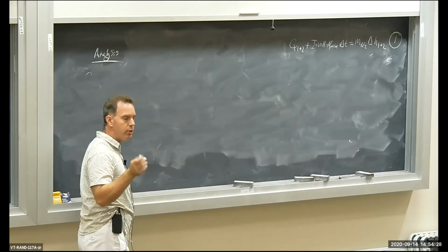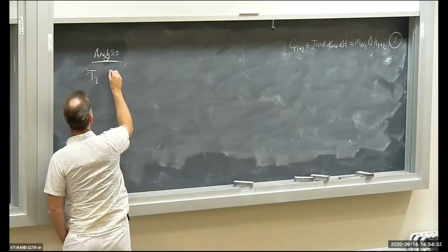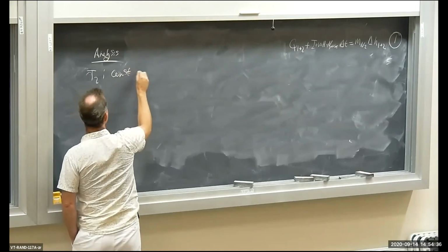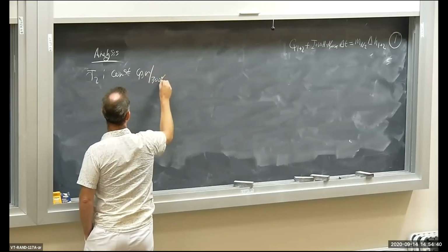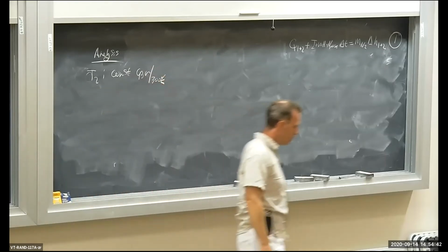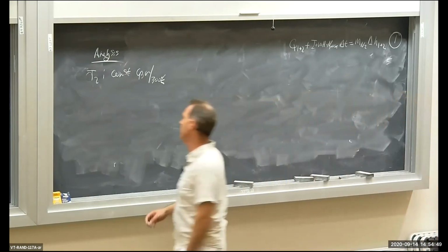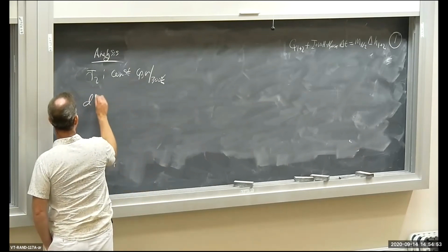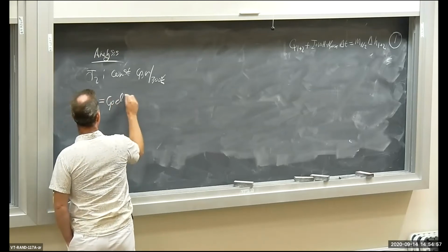Let's calculate T2 assuming constant specific heat, constant Cp and Cv evaluated at 300 degrees Kelvin. Let's recall the property relationship for enthalpy: dH is equal to Cp dT.